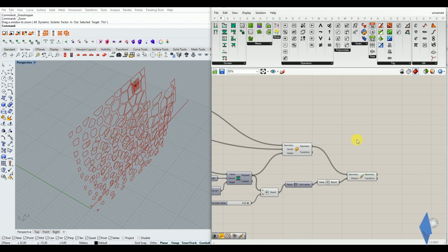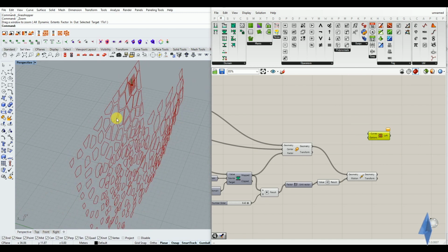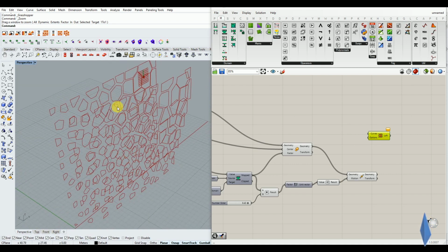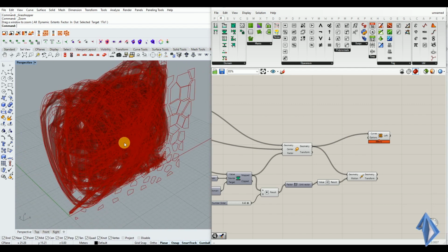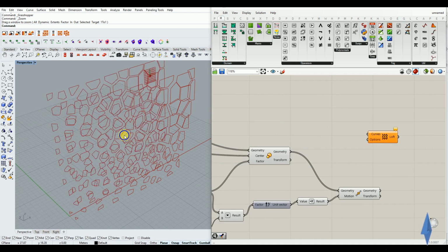Now let's understand why we need to graft them. If you double click and type loft, bring in the loft component, which means I would actually like to extrude all the curves to their respective curves, and I would like to create a 3D form between all of these curves. So if I just attach geometry to curves, it would create a haphazard, confusing thing like this. This is exactly why you cannot attach a flattened list to this particular input. So just do Ctrl Z and go back.